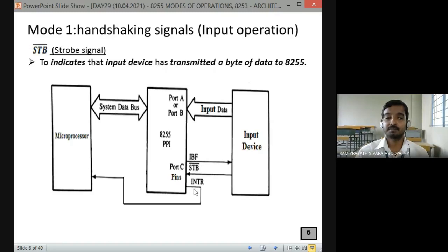Fine. So here we are speaking about port A, let us assume. Now the data has gone and got stored in the port A input register. Whether it can receive any data now, can it take more input data? See, I am having an 8-bit register. The input device is giving 8-bit data. I am receiving. Once I have received, I have no space to store the next data. Correct? When can I receive the next data from the input device?